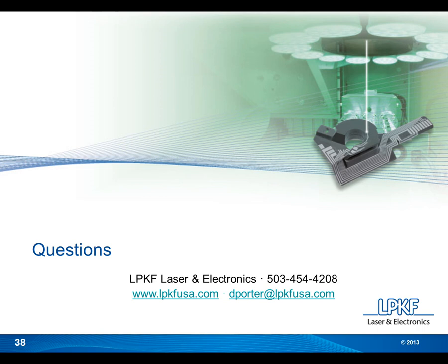do the metal ion loaded plastics have additional useful properties? For example, thermal or EMC? Well, not usually, actually. It does change the properties of the plastic somewhat, so we typically minimize the amount of dopant that we put in any specific plastic. When we qualify a certain thermoplastic, we're usually working with the minimal amount of dopant that we can add to get good plating and good adhesion still.